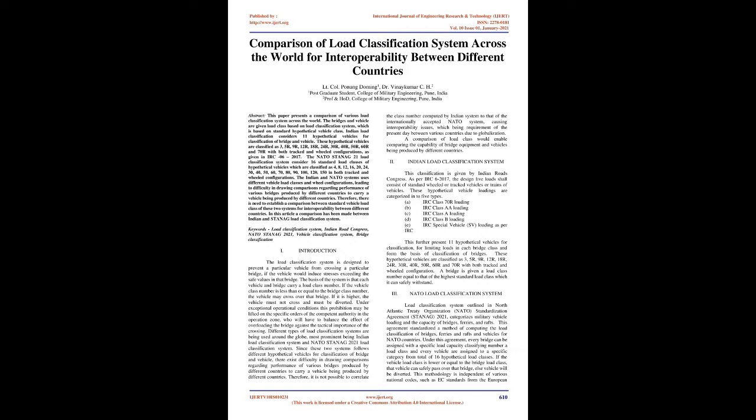Since these two systems follow different hypothetical vehicles for classification of bridges and vehicles, there exists difficulty in drawing comparisons regarding the performance of various bridges produced by different countries to carry vehicles produced by different countries. Therefore, it is not possible to correlate the class number computed by the Indian system to that of the internationally accepted NATO system, causing interoperability issues, which is a requirement of the present day between various countries due to globalization. A comparison of load class would enable comparing the capability of bridge equipment and vehicles being produced by different countries.